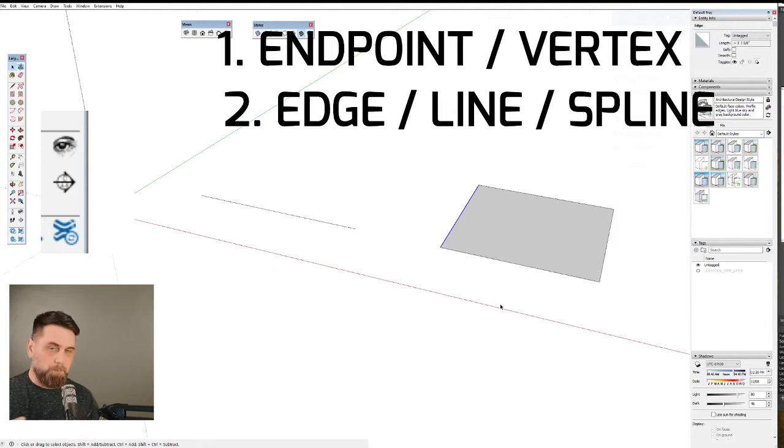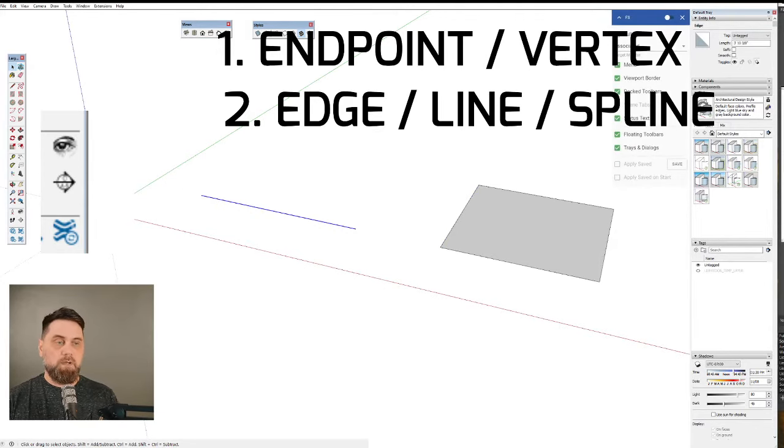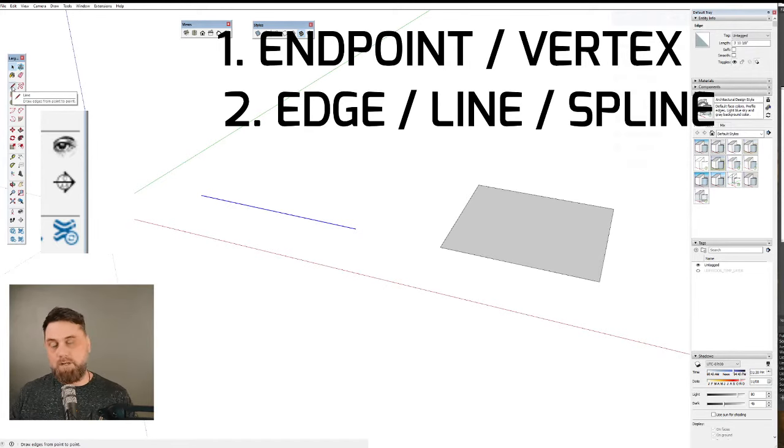So it's supporting a framework. It's a part of a circuit that now has a closed face. However, in SketchUp, it just calls it edge all the time. So it gets a little bit confusing, though, because the tool to create edges is called the line tool. So understanding the universal way that those terms can be interchanged is important.